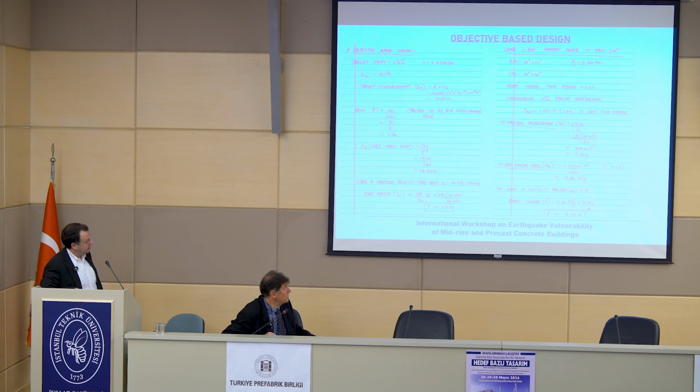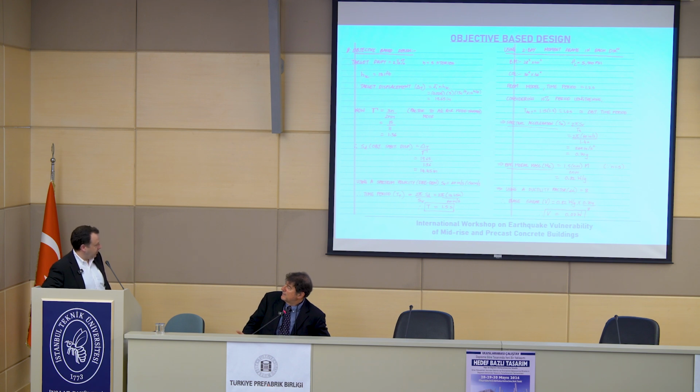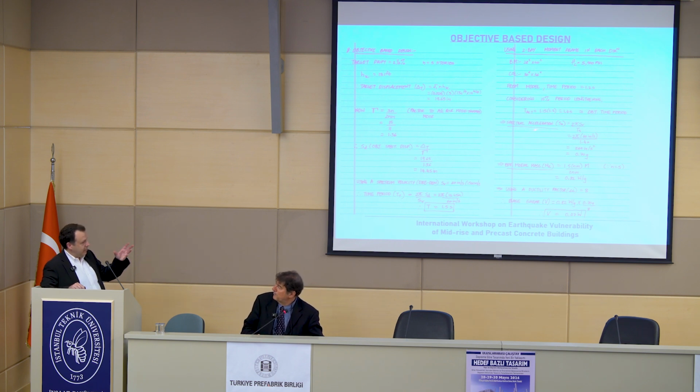So you're multiplying the period which you found in your ETABS solution by augmenting like 20%, 15%, something like that, to sort of reach this estimated target period. It's a lever that you can use, or just adjust the dimensions.